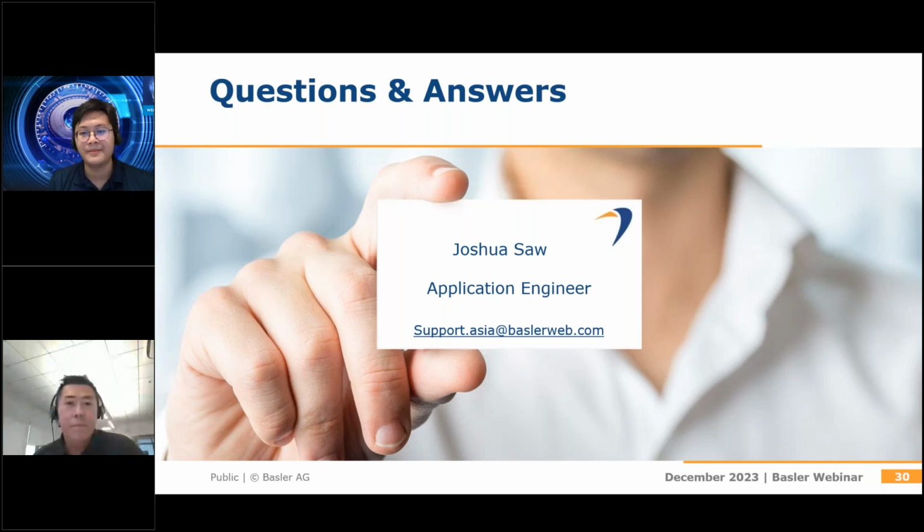And we have the last question: can I use an NIR or SWIR camera with a liquid lens? Yes. The standard liquid lens supports a wavelength between 400 nanometers and 950 nanometers, and there are also options that work with a wavelength range between 850 nanometers and 1600 nanometers.